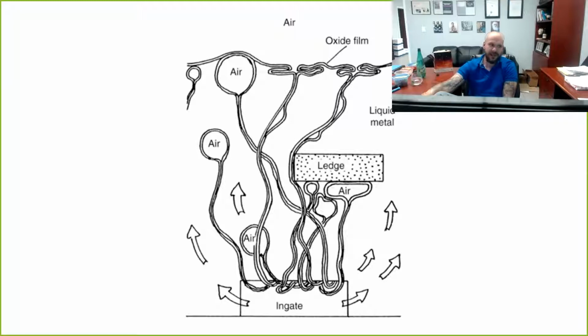Here's what happens when air bubbles start entering your casting cavity. Metal casters for generations have known that during the pour, air is being aspirated. Most foundries, you can hear it. You can hear the gurgling, the slurping, the popping. Traditional wisdom has been, as long as the air bubbles have a chance to rise through the melt and they escape the surface of the melt and we don't have a pre-solidifying skin, we're going to be okay. Traditionally, when castings have subsurface porosity, foundries will just pour the casting a little bit hotter, and their theory was that'll get rid of the bubble. And while it got rid of the tiny little bubble deposit at the surface, which we'll look at in a second, it did nothing to change the fact that the casting was completely damaged.